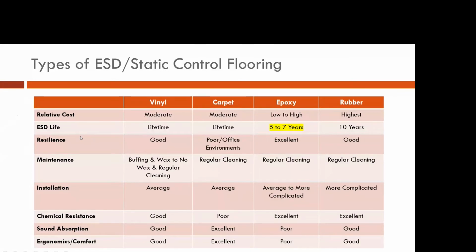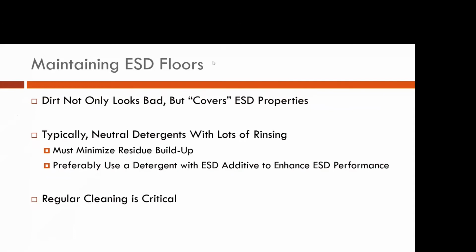So maintaining your ESD floor. So this is ultimately important because, you've got really, a couple of things. You're concerned with aesthetics, but with an ESD flooring, function becomes primary, right? And if an ESD floor has dirt and debris that's built up upon it, what's going to happen is that sits on top of the floor, and that creates an insulative barrier between the floor, which could be connected to ground and functioning properly, and the operator, who could be wearing their ESD shoes or footwear. Now there's this microfine layer of dirt, dust, debris, residue from cleaning products that is a built-up insulative barrier.